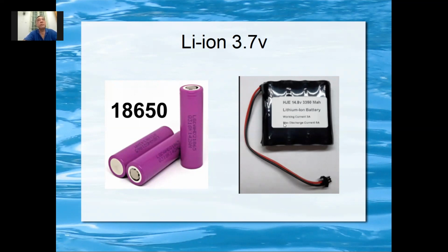Okay, and sometimes they put these lithium ion batteries, they pack them up, 4 pieces, 8 pieces, whatever pieces, and just solder them together. But what you cannot see here is actually an electronic load balancer. Without this load balancer, you cannot charge the battery. The battery will overcharge, because if you put them in series, then you have a problem.